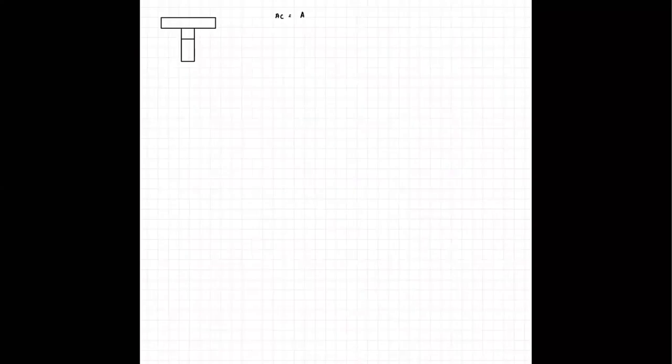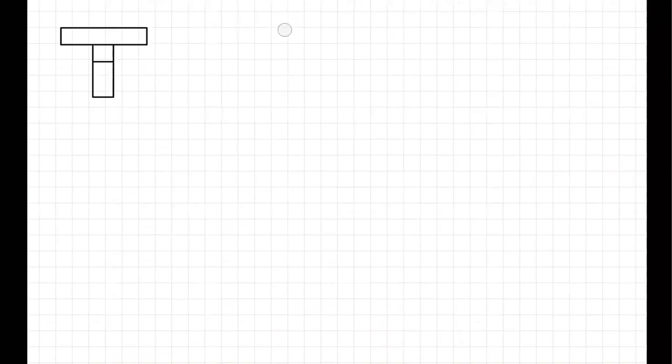And then we proceed to ASF since it is already a true T-beam. So step 8 in our procedure is to calculate for ASF. That is 0.85 F prime C times BF minus BW times HF all over Fy.